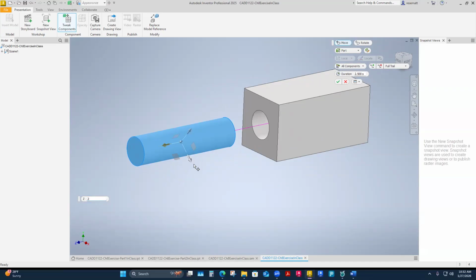Because right now I can tell the way these planes are, probably in relation to the origin planes on the part. And I did an axial alignment here on the axis, but I never did a plane alignment to stay true and flat necessarily. On a round thing, it doesn't seem like it would matter, but it kind of matters if I'm manipulating it here, because it wants me to pull these based off its origin planes. And it'll be weird. They're not going to be in alignment with these origin planes potentially. I can tell they're not. They're all kind of crooked here compared to how that one sits.